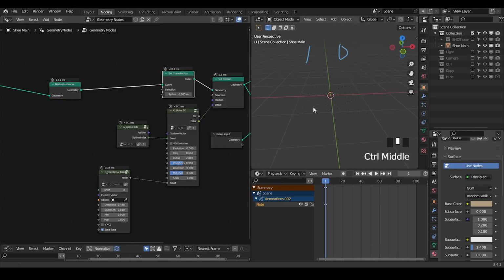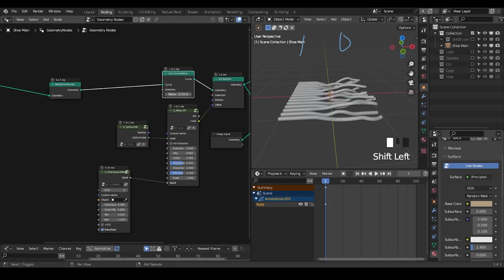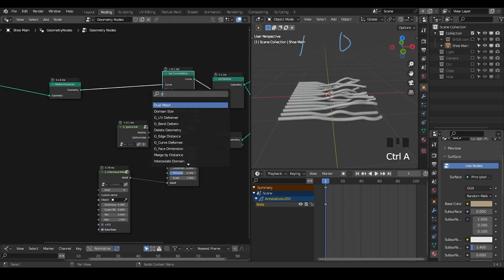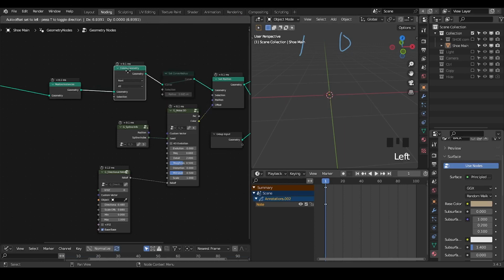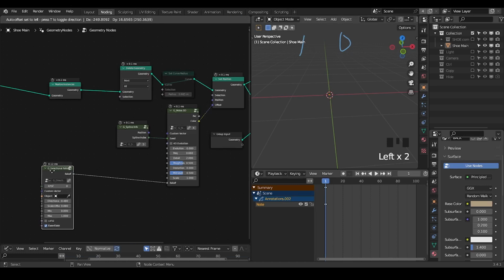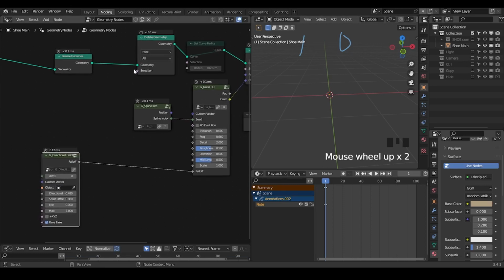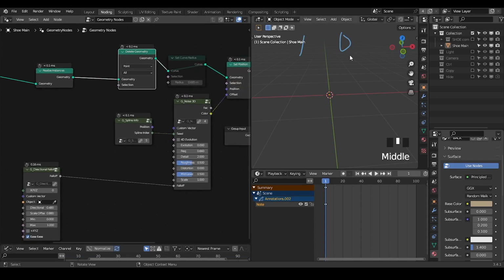When the curve is too thin, then you do not see them in the viewport unless you increase this radius size. Another method is to really delete the geometry as we discussed, you make a selection to delete some part of a spline. Right now, everything is being deleted with this selection. Okay, so these two ideas are basically the same.